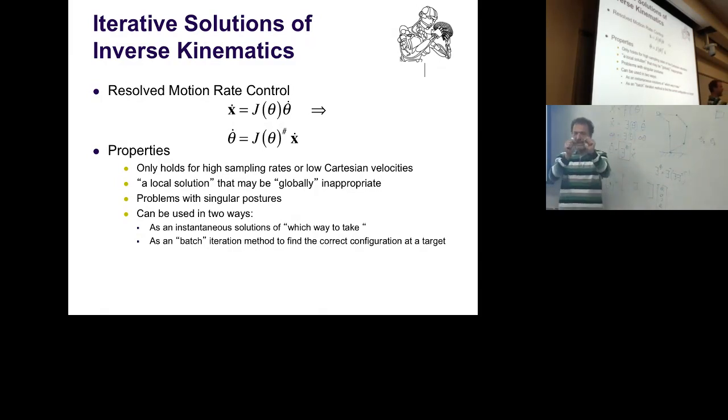Just basically put in theta end as a target for your PD controller. It will not be a pretty movement. The difference is basically that when you do a joint space movement, you usually do a curved movement. It will most likely go like this. So a straight line joint space movement does not translate into a straight line end effector movement. If you do a straight line end effector movement, it does not translate into a straight line joint space movement.